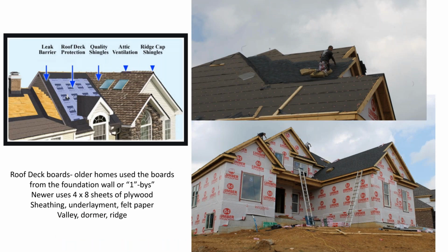As I mentioned before, in the old days, they used to use the decking boards from pouring the foundation. Now they're using sheathing, which is typically 4x8 sheets of plywood. So you're going to have the plywood, the roofing material, then there's an underlayment again to help prevent the water intrusion, and then you're going to put the shingles on top of that. Where the shingles meet on an angle is called a valley. So this is going to be the valley right here. Sometimes it'll have a copper valley, just a chute, and sometimes it'll just overlap the shingles. So if you see something on your inspection report that's talking about the valley, that's what they mean.